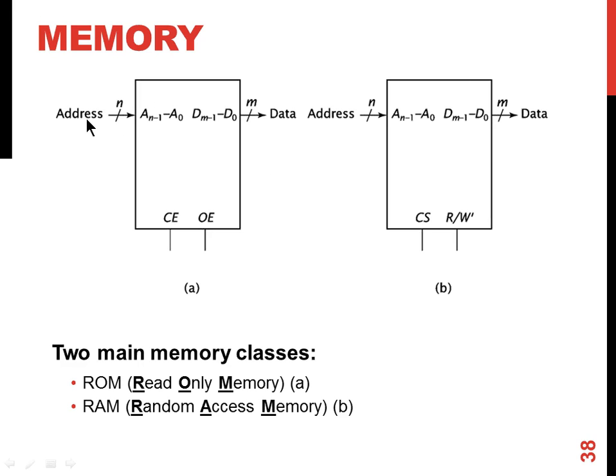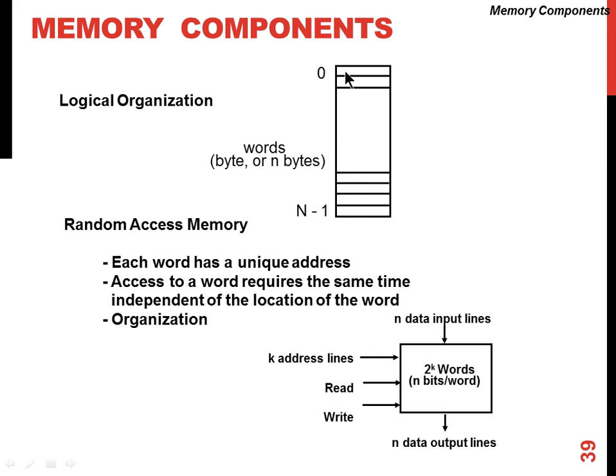So your memory could have a depth, and each location has a width. To address a particular location, or to use it as an index, we need the address port here, which will be used as an index to address a particular location of the memory. So this is the depth of the memory, and each location could be 1 byte or more than 1 byte, depending on how your memory is defined. As we said, it will be a read operation. We can read from the memory or we can write to the memory.